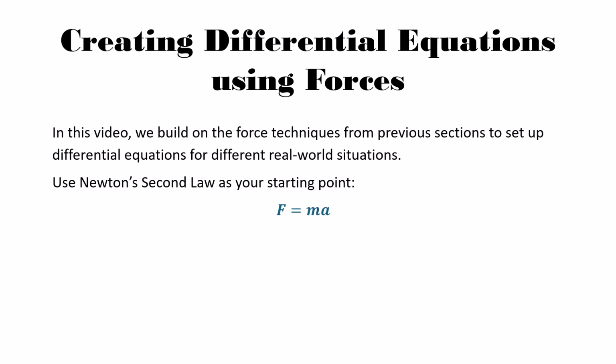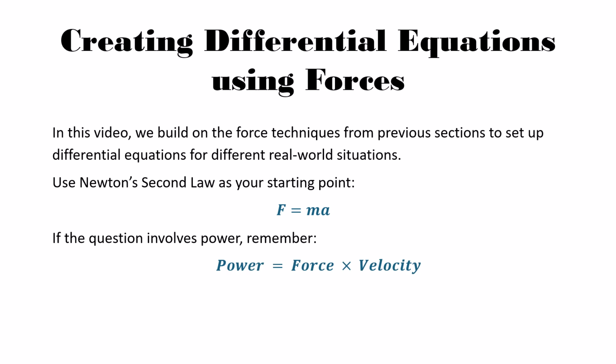So we're going to use Newton's second law as our starting point. We're going to use F equals ma, and we're also going to be bringing power into this. Just remember power is equal to force by velocity. Or for a way to convert your power into a force, we're going to do power divided by velocity.